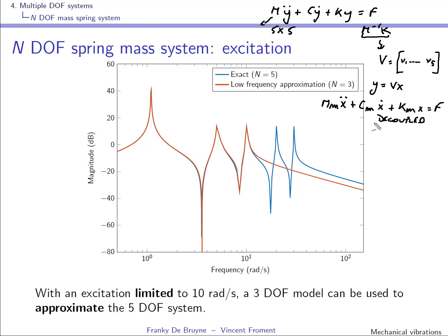Okay, so you can look at 5 different mass spring systems, and you can find the solutions x1, x2, x3, x4 and x5 and stack them in a vector, which we'll call x bold here, and you can then reconstruct the solution of the original problem by simply taking this modal matrix V times the vector x, which gives you the solution of the original problem.